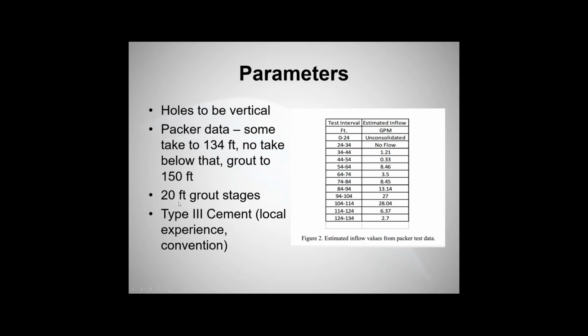Important thing here, I really didn't talk about it before. Stage length, hugely important when it comes to consolidation grouting. I could probably do a whole presentation or a third of a webinar on why. But typically, 10 foot is probably the best stage length. It gives you the best, most economical grouting cycle that you can get. However, long holes, sometimes we go up to 20 foot. Typically, we will not want to exceed 40 foot for a hole done from the surface.